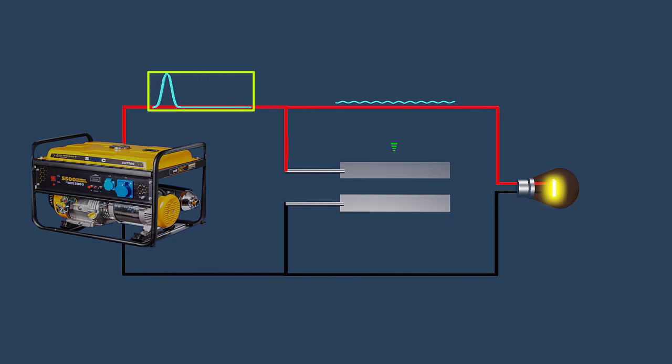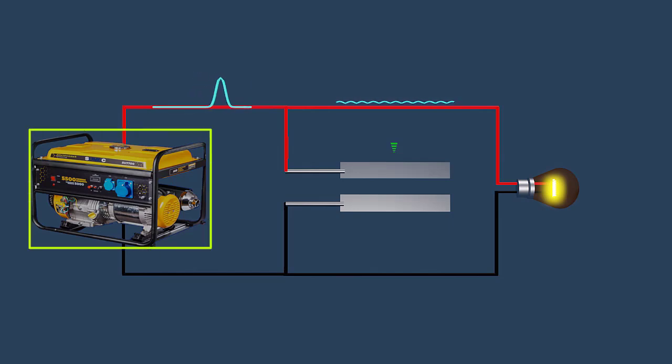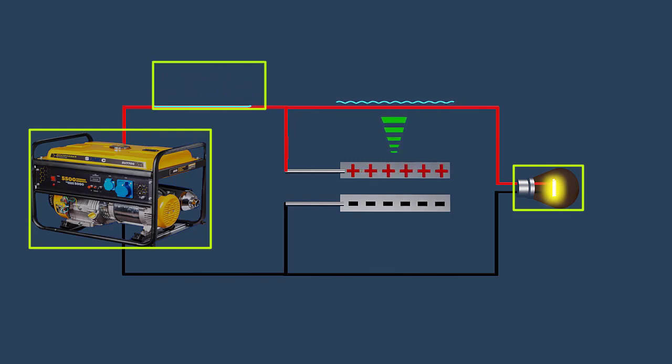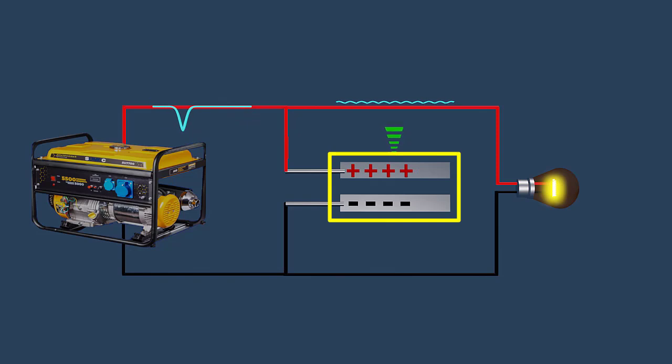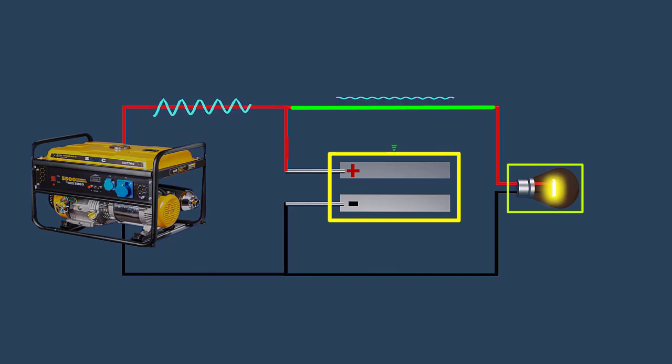During periods of high voltage, the source powers the bulb, and the capacitor rapidly charges, absorbing excess energy and preventing the voltage from rising too high. During periods of low voltage, the capacitor discharges, releasing stored energy to maintain a constant level of the output voltage across the bulb, ensuring a steady flow of current and preventing the light from flickering.